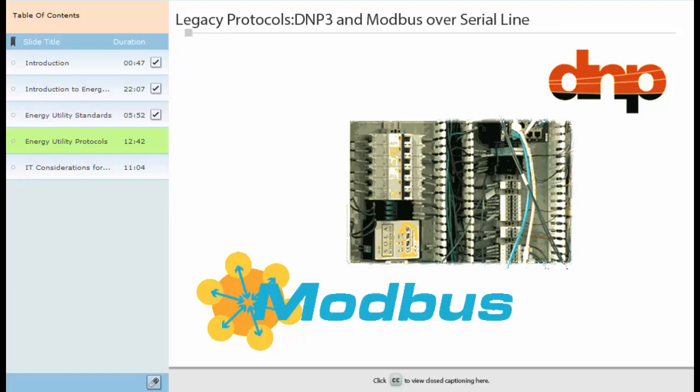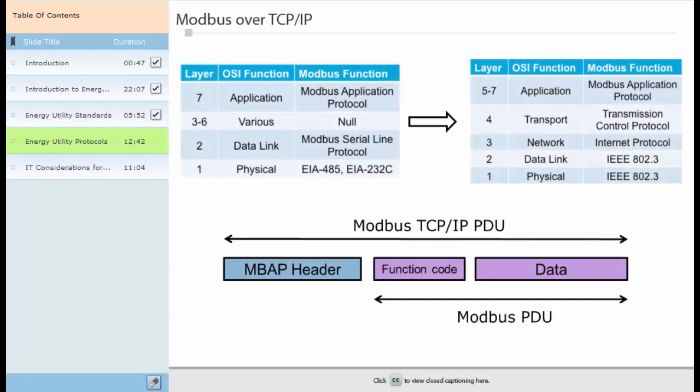Modern industrial networks have changed so organizations can operate over longer distances and wider geographic areas, which is why DNP3 was adjusted to use TCP/IP for the transport and network layers and the Ethernet protocol for the physical layers. The Modbus protocol is still in use in the automation world because it can connect IP Ethernet networks.